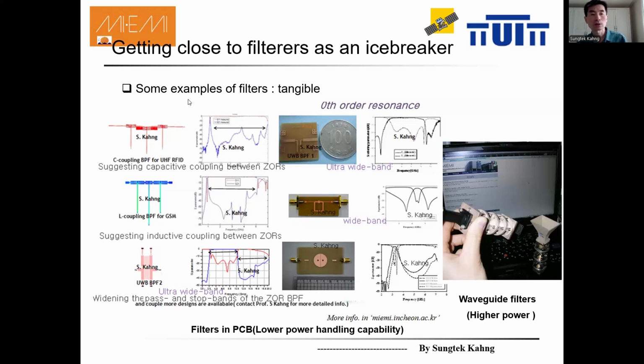Zero times n, where n means the nth harmonic. Ideally or theoretically, harmonics don't occur, as you see. But this point and this point are the real ones. Why? The self-resonances occur from certain blocks of the filters, but these blocks are already small, and the level of suppression is already high.